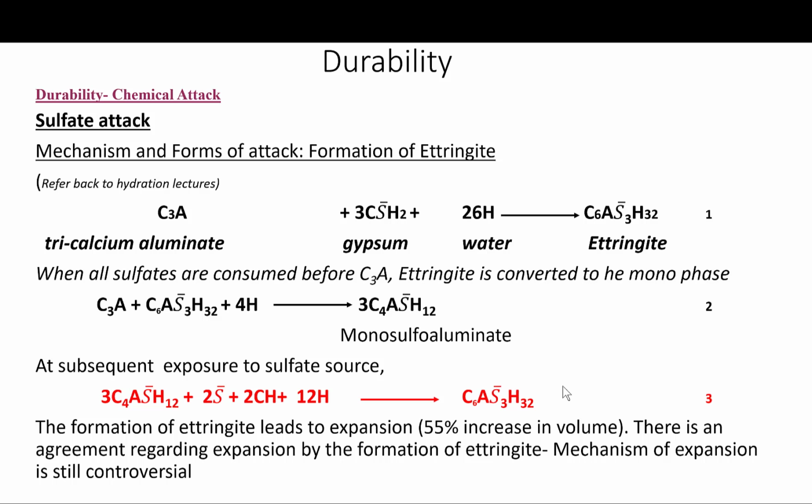The exertion of pressure by growing ettringite crystals, and maybe the swelling due to the absorption of water in an alkaline environment by poorly crystalline ettringite. The ettringite that forms in an alkaline environment is usually poorly crystalline. So the absorption of water and the resulting swelling. These are two of the several hypotheses out there, and they are basically supported by most researchers.